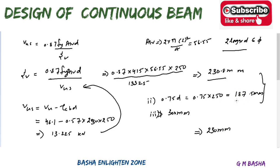Sorry, I am not checking with this one. Your lesser value will be 187. Therefore, provide two-legged 6 mm stirrups at a spacing of 187 mm center to center. It is not possible to keep 187, so therefore take a rounded-down value, 180 or 185 mm center to center, like that. Okay.